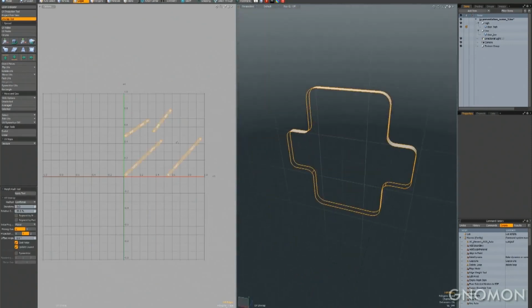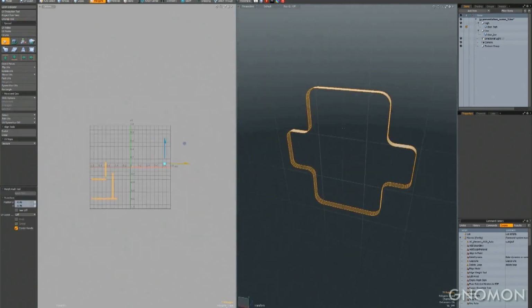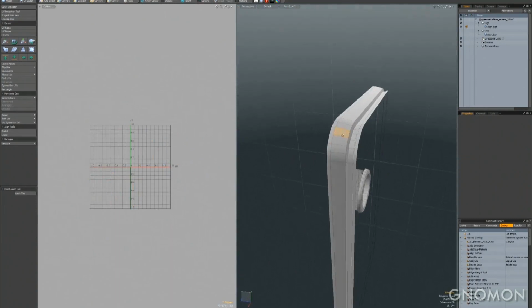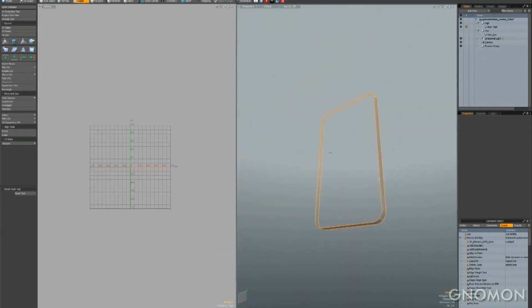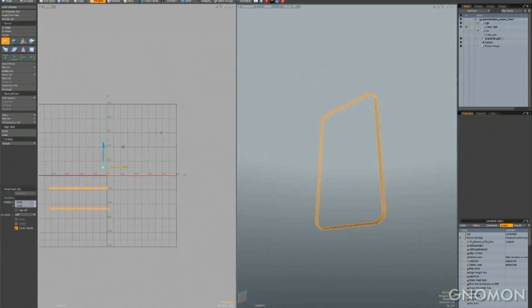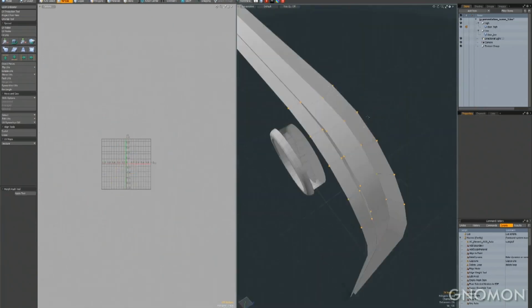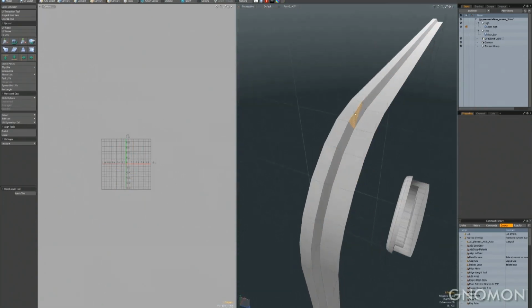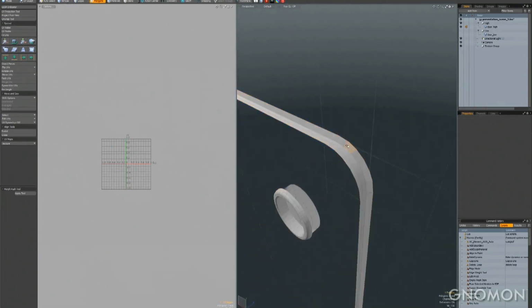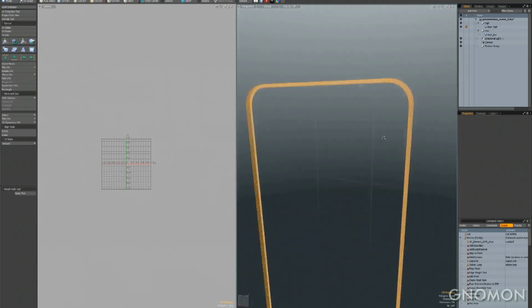Super handy, super useful. We'll do the same thing right here too. You should just make those into nice rectangles right away, one click. It works every single time. The way I unwrap a lot of my stuff is I'll just select edges and run the unwrap command, and it will make my shells. All I have to do is run the rectangle tool or a relax, and then just orient and pack, which will automatically shape my UV shells proportional to the X or Y axis.